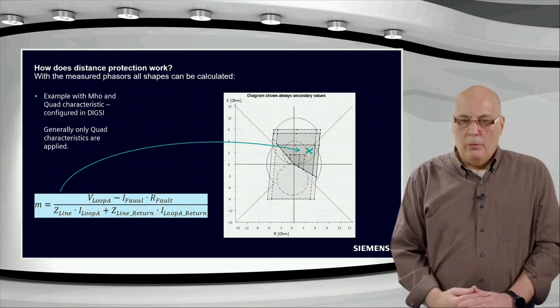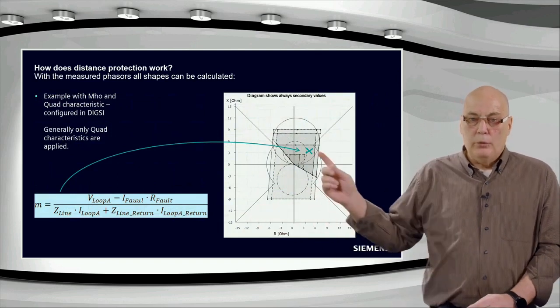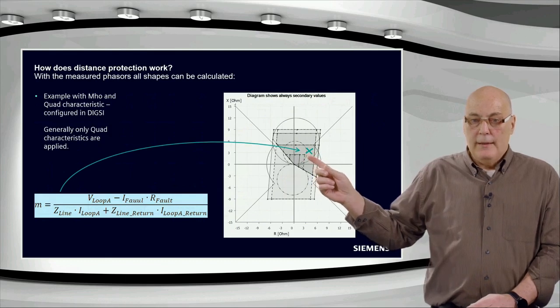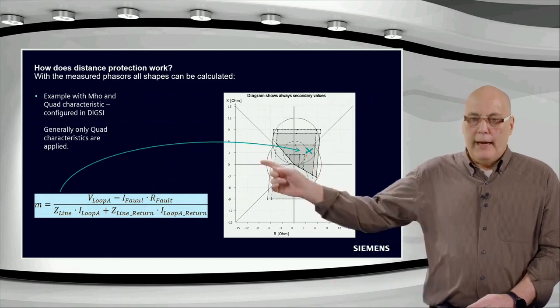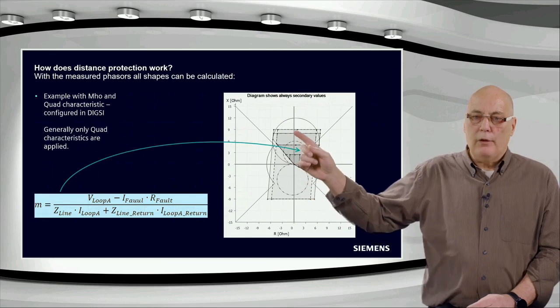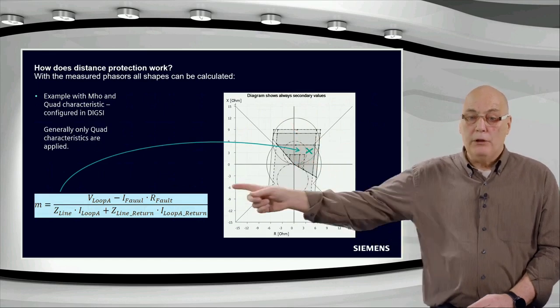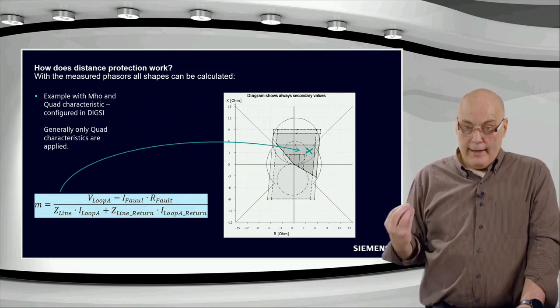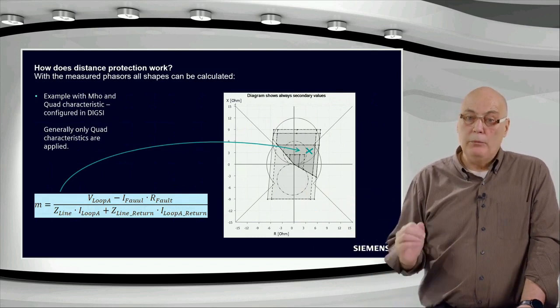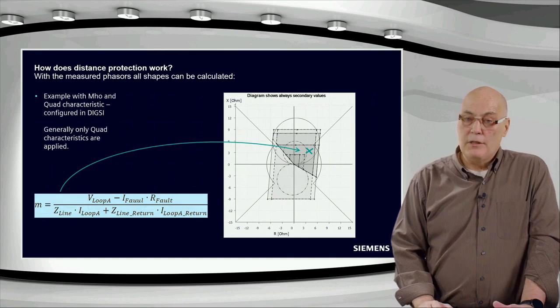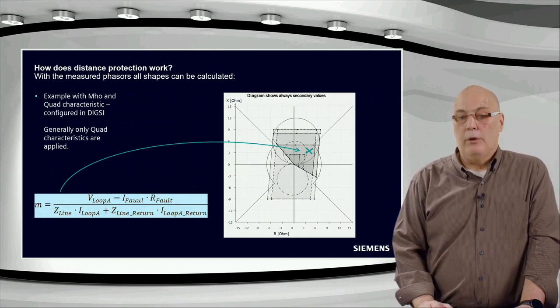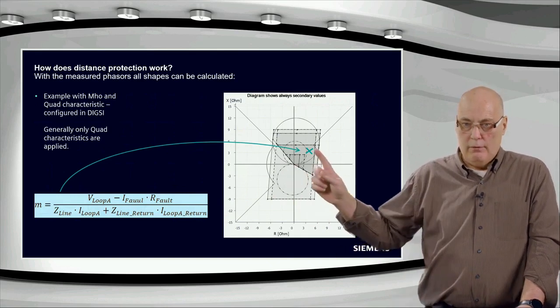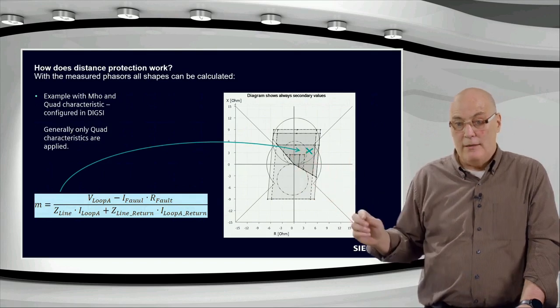If we, for example, solve for this M over here, then we would know essentially exactly where the fault location is, but the M would imply that the fault is on the line. Okay, so we would have to measure the R fault separately. So once you have extracted M as the location, assuming the fault is on the line, it is just a percentage, remember, and we'd have to convert that back to a location in a characteristic. So that's the interesting thing.